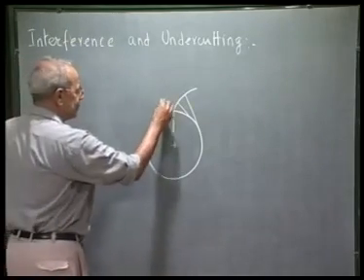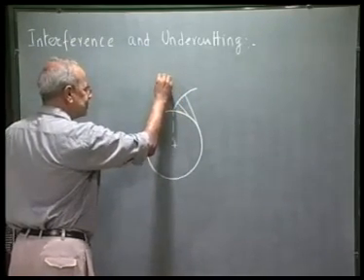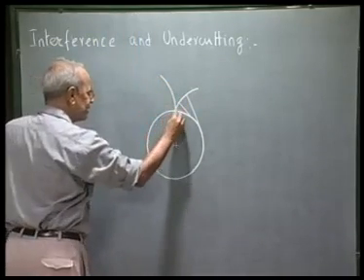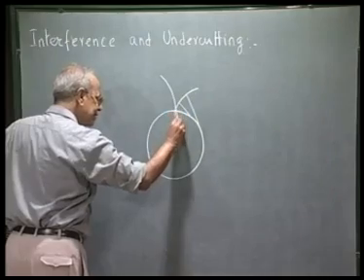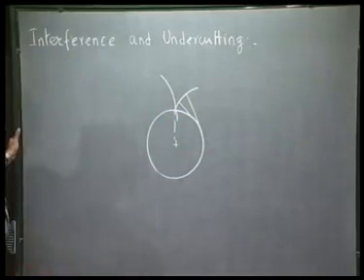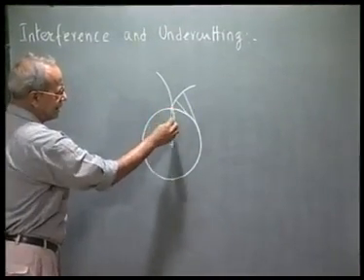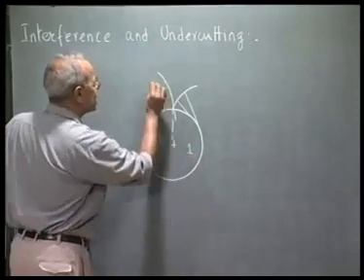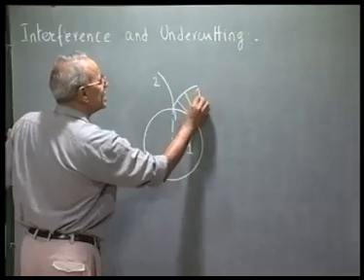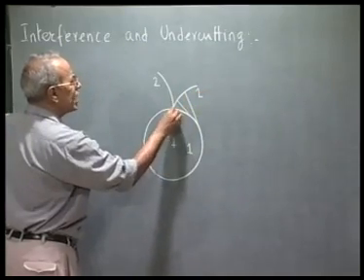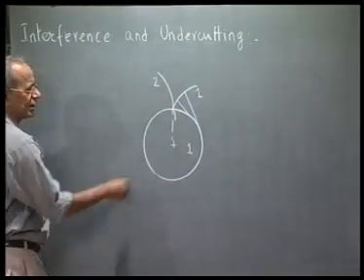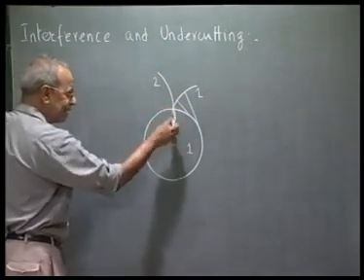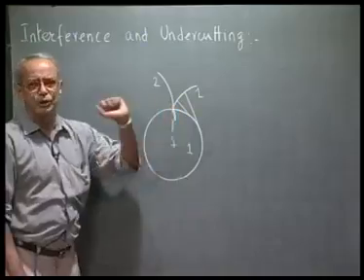But if the mating profile, which is another involute from another base circle, gets inside the base circle, as we see there is no involute of this gear, say this is gear number 1 and this is 2. The gear number 1 does not have any involute inside this base circle, whereas the involute of the other mating gear is getting into the base circle. So there is no conjugate profile.